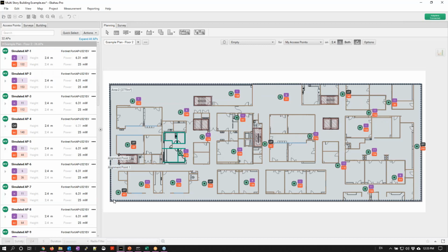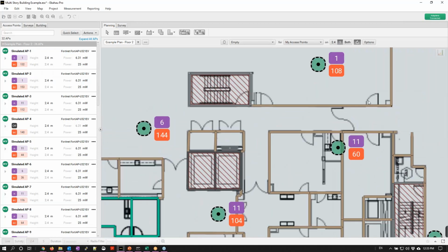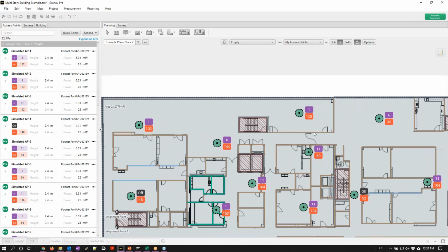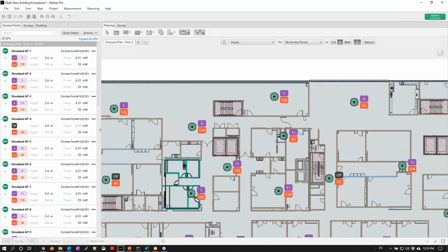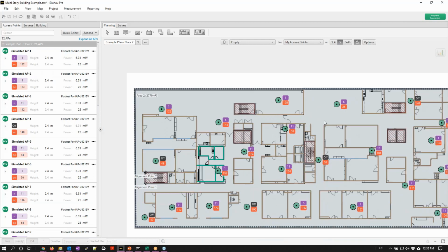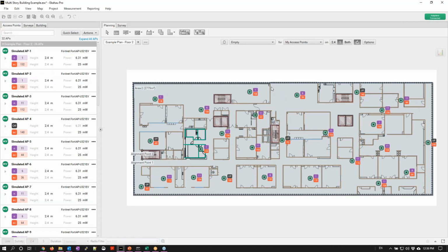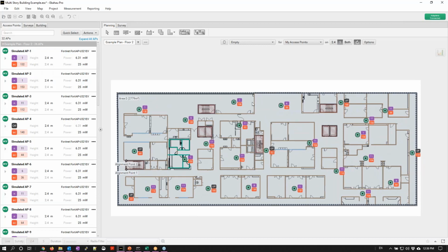And obviously, if we go to this particular doorway, if that was say 1.2 meters over a small site, the variance isn't going to be great, but over a large site, if you're missing 200 mil, it starts to impact the signal spread of how it's represented in Ekahau as well. So trying to attain the most accurate floor plans from the customer is highly advised. And of course, it produces the best results as well.